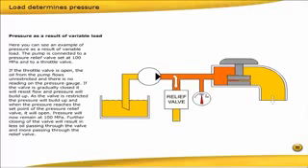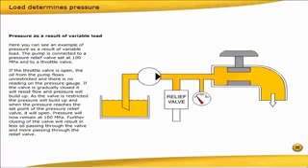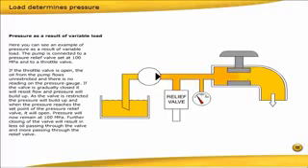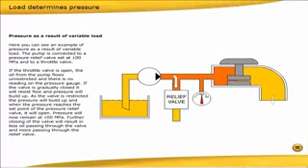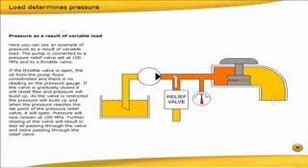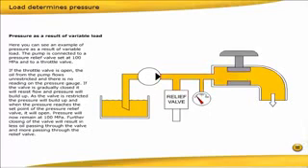If the valve is gradually closed, it will resist flow and pressure will build up. As the valve is restricted, the pressure will build up, and when the pressure reaches the set point of the pressure relief valve, it will open. Pressure will now remain at 100 megapascals. Further closing of the valve will result in less oil passing through the valve, and more passing through the relief valve.